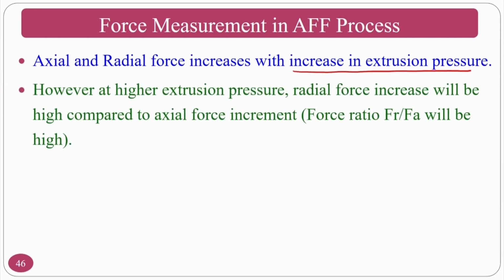However, at higher extrusion pressures, if I am using 3 megapascal, 4, 5, 6, 7, 8, 10 megapascal, that is, a 100 bar or 10 megapascal pressure, the increment of the radial force will be high compared to your axial force. What I mean is, if I have 5 megapascal, assume the radial force is 5 newtons and the axial force is 10 newtons.